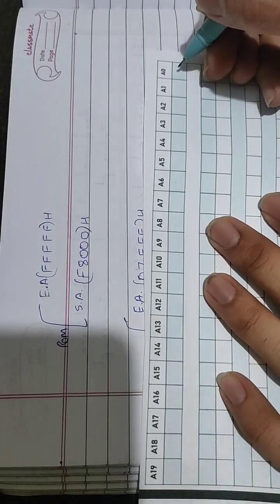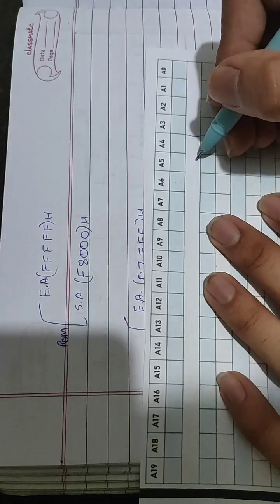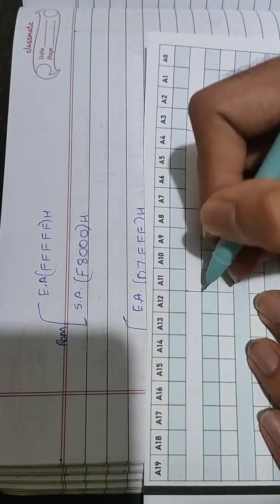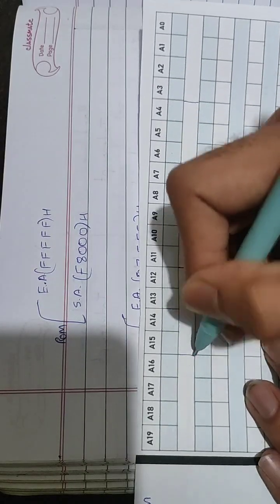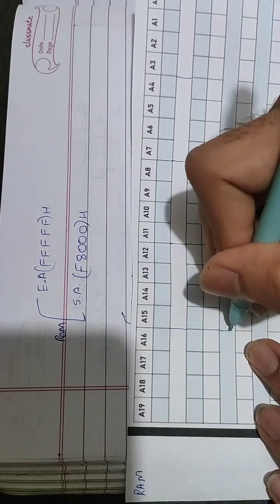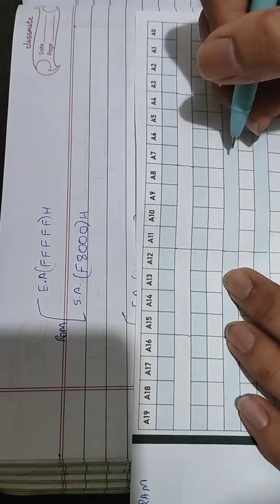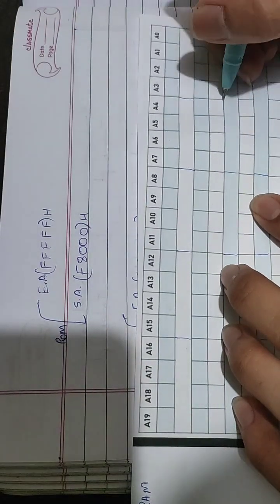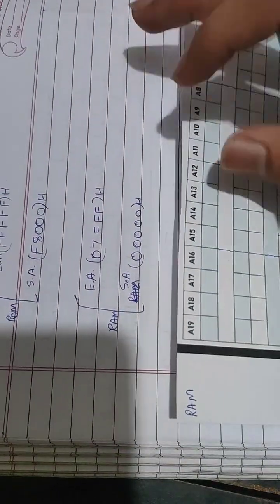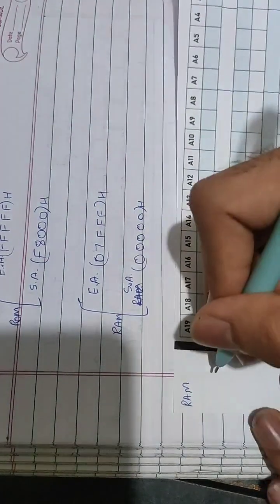Now firstly you need to group 4 bits. So 1 2 3 4, group them. Then again 1 2 3 4, group them. 1 2 3 4 group, 1 2 3 4 group. And you can do that down here also. These can be also grouped. So you have 4-4 pairing, no? Now we already know the RAM's starting address and ending address. However, now we are concerned with odd bank and even bank.